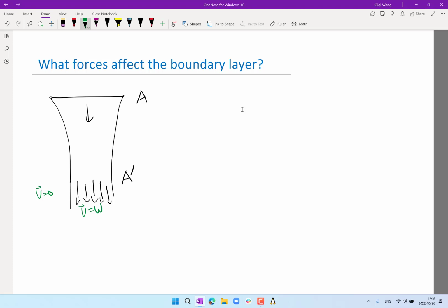Yeah? It's no longer isentropic because you've done work to it. It's no longer isentropic. Yeah, that's right. Okay, so yeah, so there are two ways to think about why it is not true. One way is to follow the streamlines, right? If you follow the streamlines, we know Bernoulli is always correct when you ignore viscous forces, when you follow a streamline. But the problem is when you cross here.